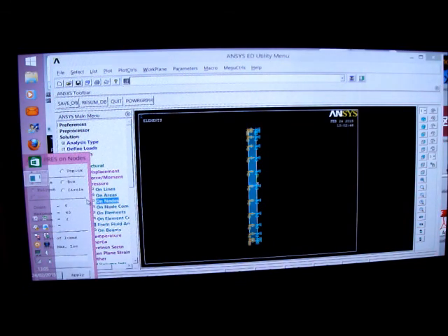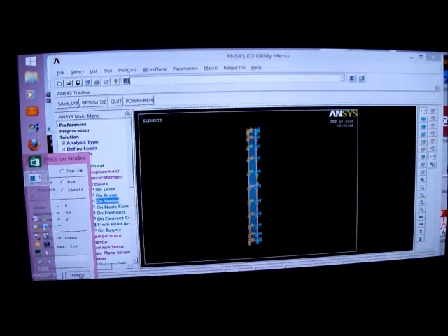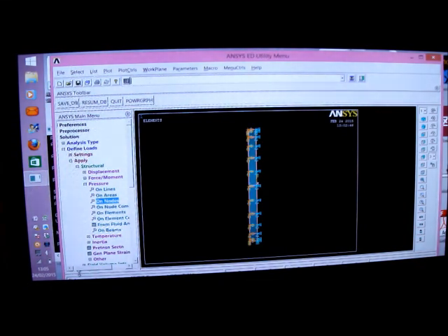Now the pressure for the eigenbuckling pressure for this, so we put pressure on nodes. The eigenbuckling pressure for this, we'll box this in here, was about 8,000 megapascal. It was huge, so I've got to put in something a bit smaller than that, see if it works. We put in minus 1,000, and I press apply, and I'm going to stop now because when I do this analysis it might take 5 minutes, so I'm going to switch my camcorder off.